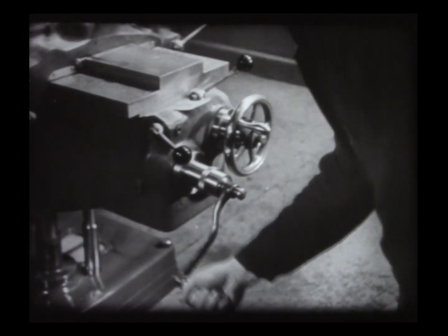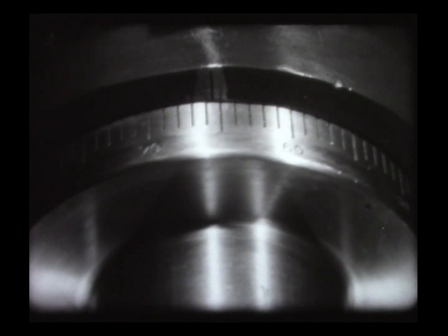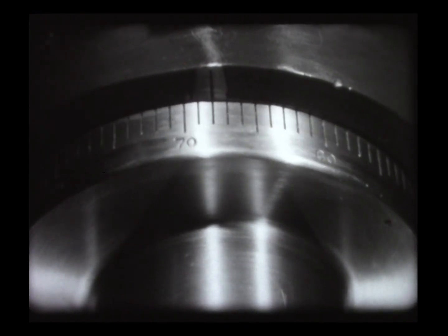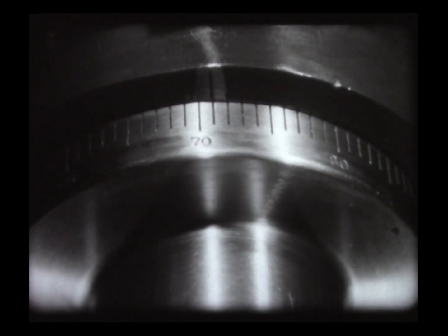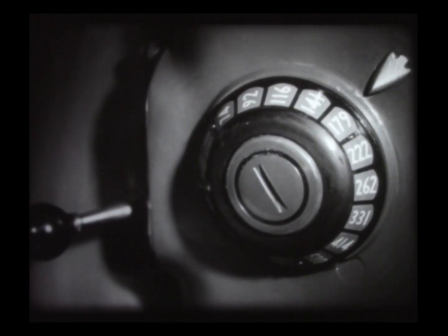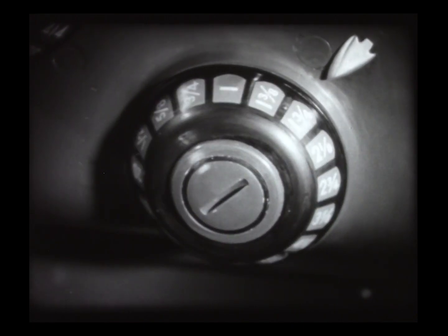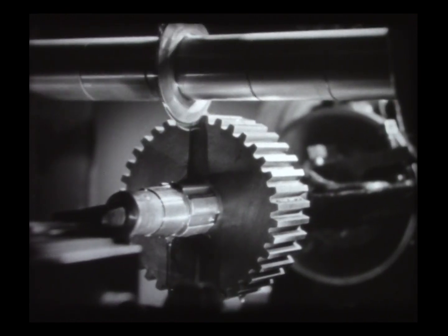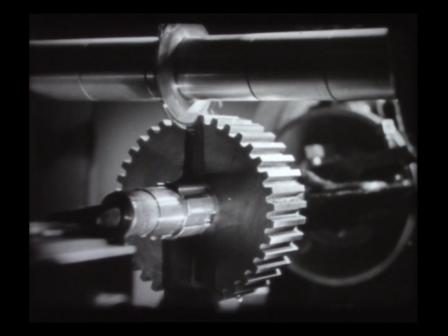For the 1/16 inch finishing cut, the table is raised an additional 62 1/2 divisions from the starting point of 7, giving a final reading on the vertical index dial of 69 1/2. Since the depth of cut is small, the speed is increased, and the rate of feed is decreased to ensure a fine finish. Next, 2 trial finishing cuts are made, just deep enough to check the thickness of one tooth.